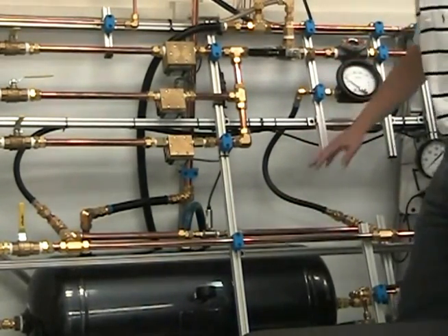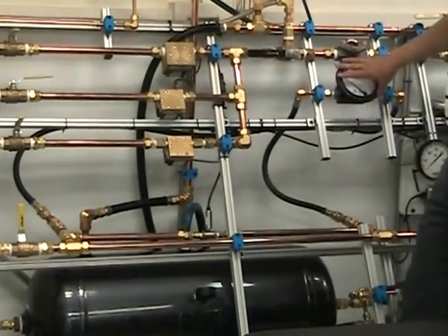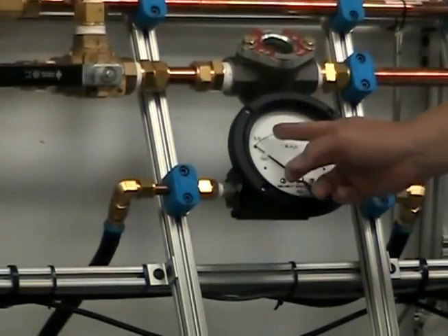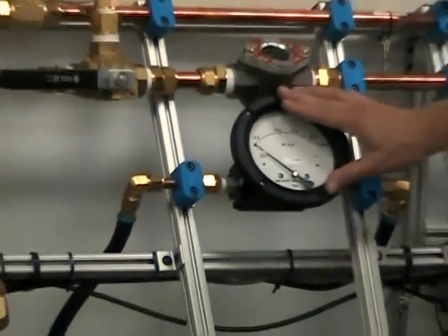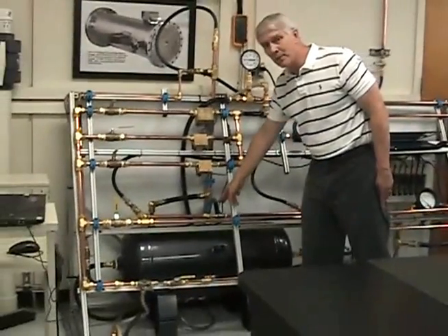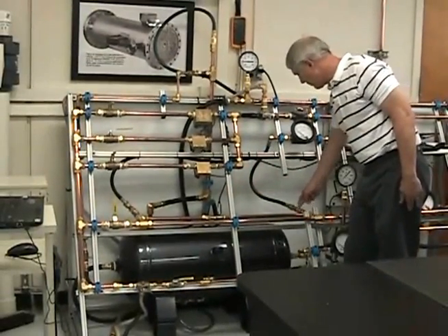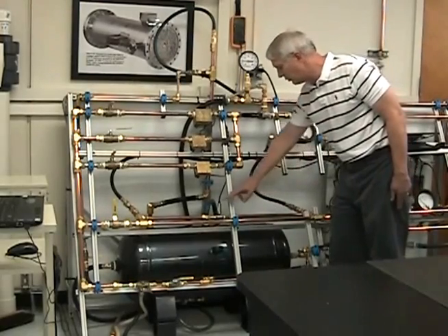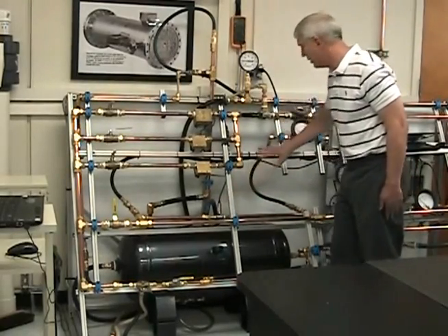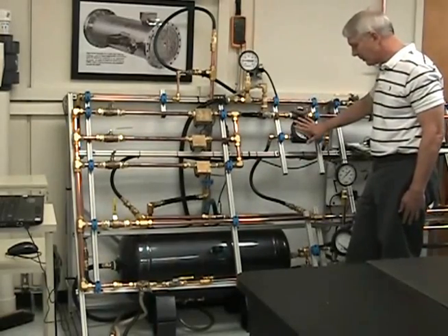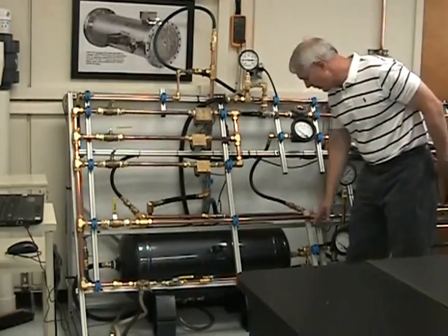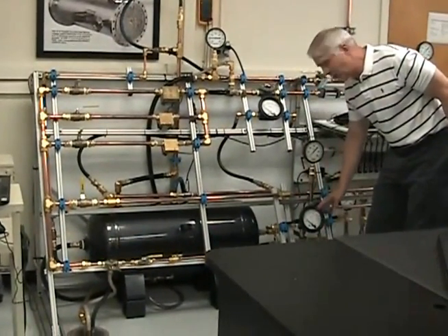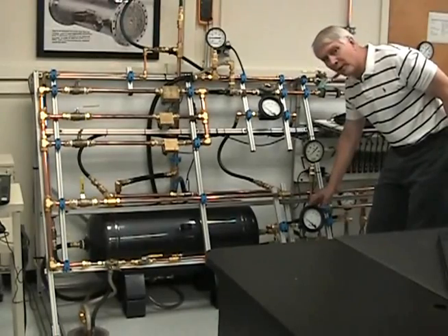So this gauge right here, you can follow the pipes here, or the tubes, but we have this analog gauge right here, so you can also look at this gauge and see what the pressure difference is. This gauge and the pressure transducer might be a little different because water can actually go up in the tubes here, and that's going to change the reading a little bit. So the transducer should be more accurate, but this will give you an idea of what's going on. We also have a transducer for the small pipe, which is located down here, and you should find that when you come to lab, and we have an analog gauge associated with that.